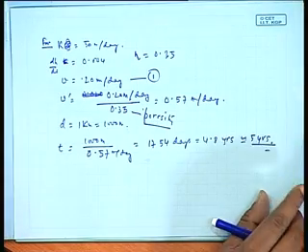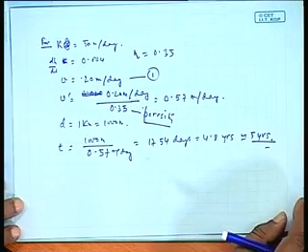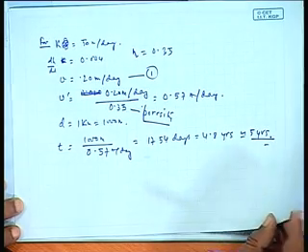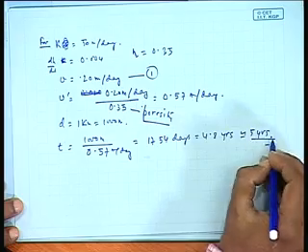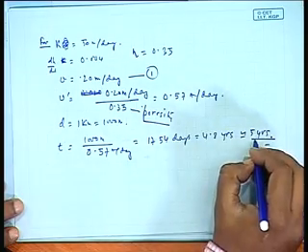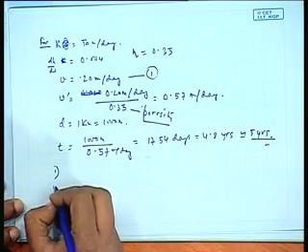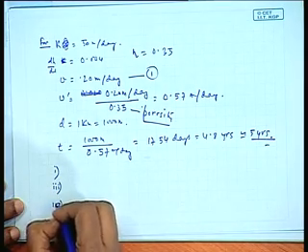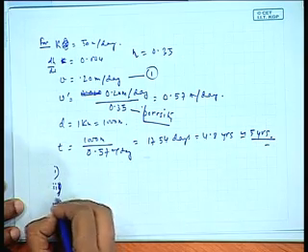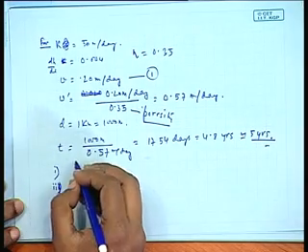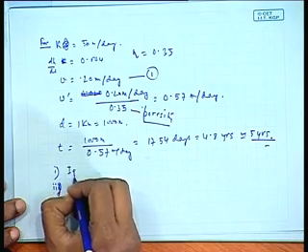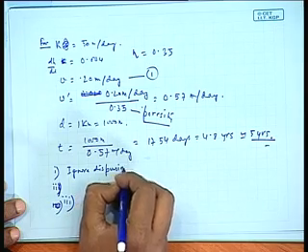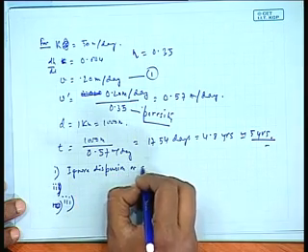Here again, as we have said, we have mostly discussed the flow, but Darcy's law does not discuss dispersion. Let me briefly put light on dispersion. There are 3 assumptions to make here, and the first is to ignore dispersion or diffusion.